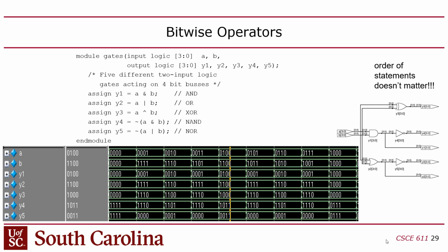You guys with me? So that's just a multi-bit signal, and then when you simulate it in ModelSim or Questasim, it'll show you all 4 bits if you put it in binary, but you can also tell it to represent these as decimal numbers or hexadecimal or octal, or I think they even have a way that it'll interpret these as floating point format too.